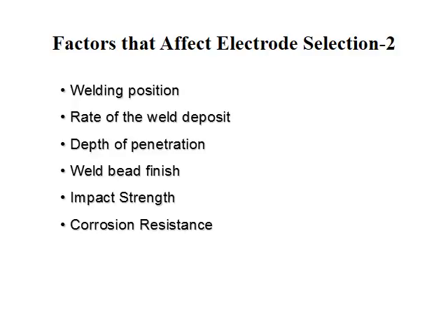Depth of penetration. What kind of material are we welding on? Is it a sheet metal weld? Well, a lot of times on a sheet metal weld, you might not want something that's really going to have a lot of penetration. Weld bead finish. This is, how smooth is the weld bead going to be? What are we looking for?